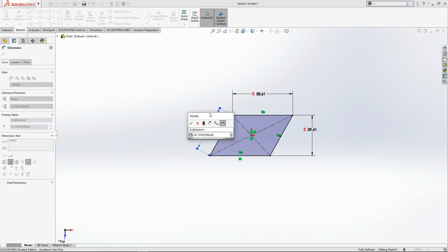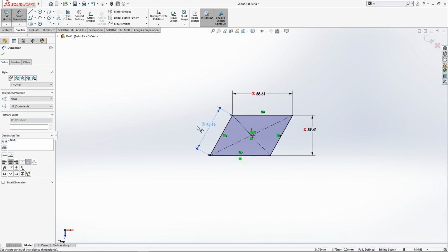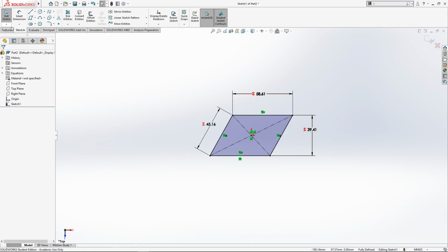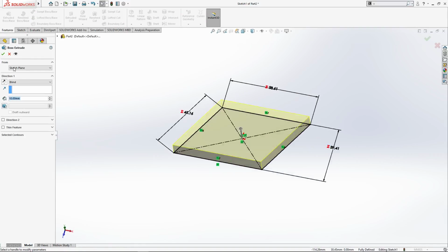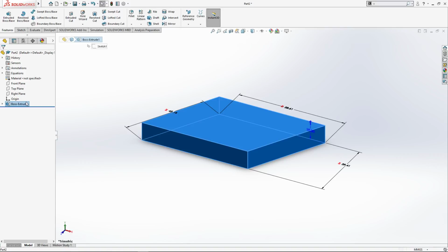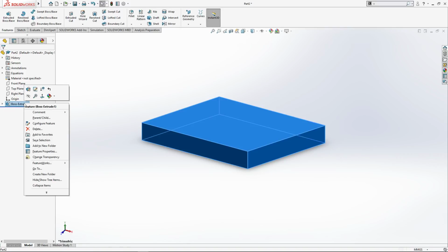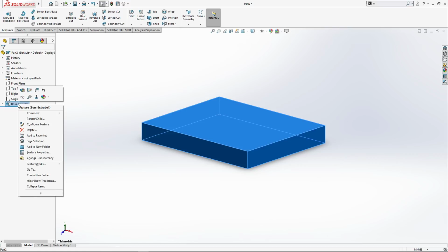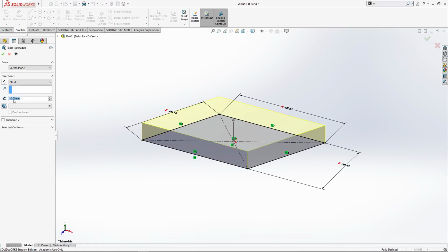We're going to start to fly through this. So that's equal to C. Exit the sketch, extrude it. Perfect. I'm going to call this the same thing. Actually, edit feature, and then for this, we're going to make it equal to P extrude. Perfect.